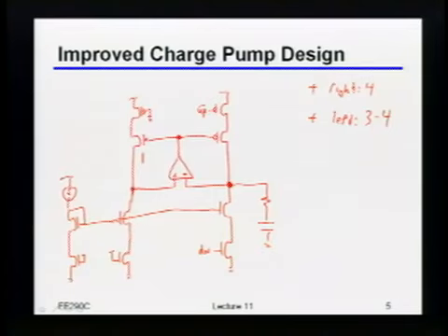But then ideally the control voltage is like DC, right? So why do you need so much bandwidth? Well, it's true that this is sort of DC, except that it's not really DC, because the loop has a finite bandwidth associated with it. So if your loop has 20, 30 megahertz of bandwidth, then roughly speaking, that also has 20, 30 megahertz of bandwidth. Not exactly, but roughly speaking. Does that make sense to people?